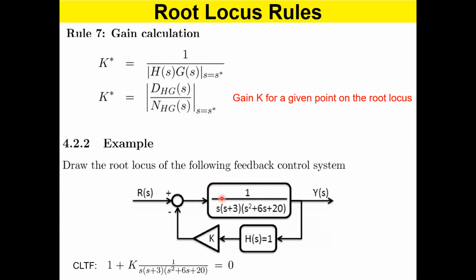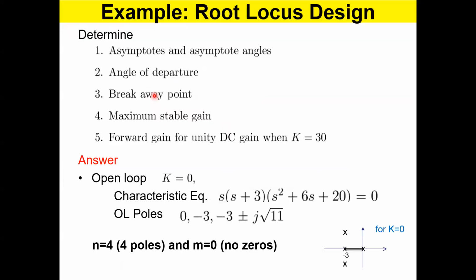So now we have only a denominator. The numerator is 1, right? So the denominator, this part comes over here, only that part. So you have to write down that part and substitute for S. The value of S is actually the breakaway point. So when they meet up at that point, calculate that value, right? We got that point using Newton-Raphson, that is minus 1.23 something. Substitute that to this equation, right? Numerator is 1, so it is basically the denominator.